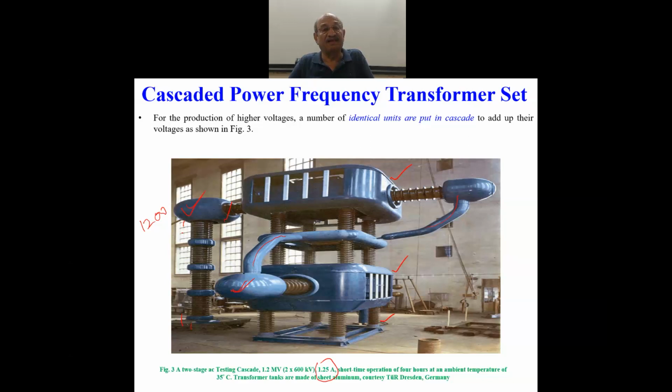The larger the radius, the Emax reduces, and you can check the partial breakdown activity by reducing the maximum field intensity around any conductor. So that is also a method of stress control for these connectors in the air carrying high voltage.